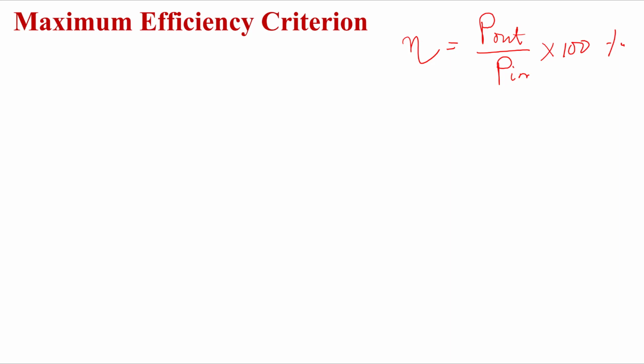Okay. So already you know the transformer. In the case of the transformer, you have studied how to get the load at which the transformer will give the maximum efficiency. What is the formula? Can you tell? Very good. Copper loss is equal to core loss. The same formula will apply here only for the permanent magnet machine, not for others.